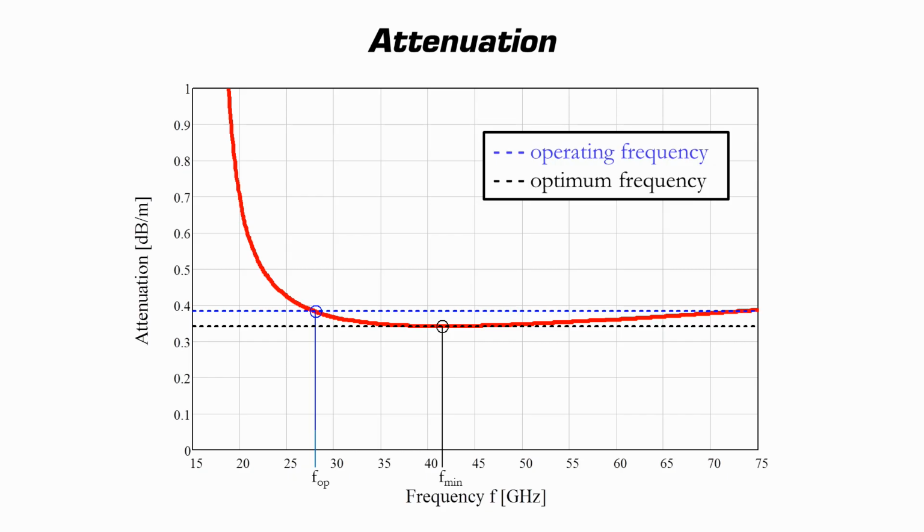Here, any waveguide discontinuity could excite higher order modes, of which 4 modes, including the dominant mode, would already propagate through the elliptical waveguide. This would result in a significant increase in attenuation due to mode conversion, as well as severe dispersion.